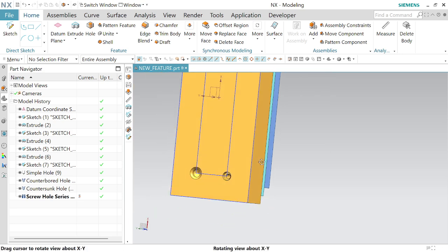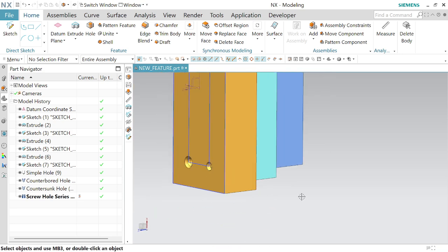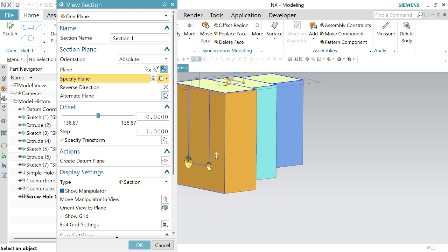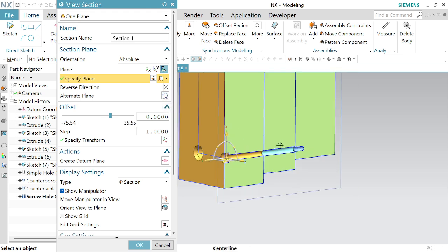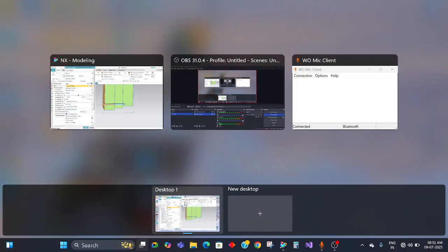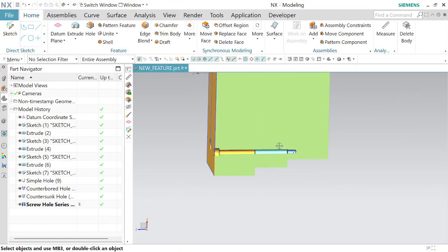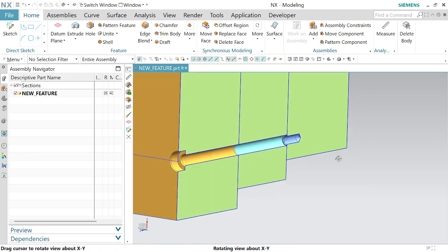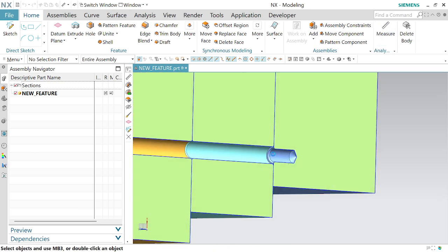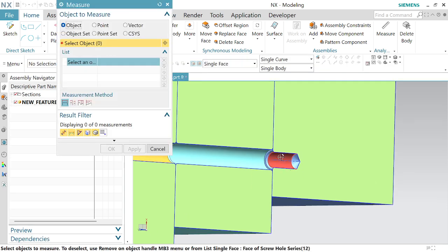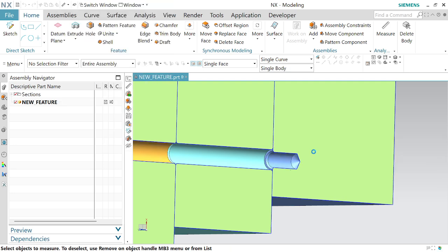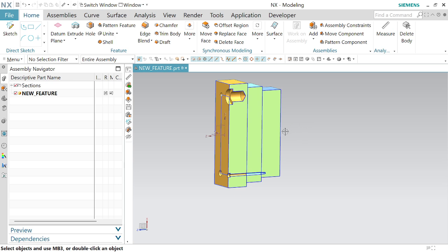So it directly created one hole, considering the standard dimensions of that stepped hole. You can check over here. If you check the dimensions of that threaded hole, it will be around 4.2 mm. It's a drilled hole for an M5 bolt.